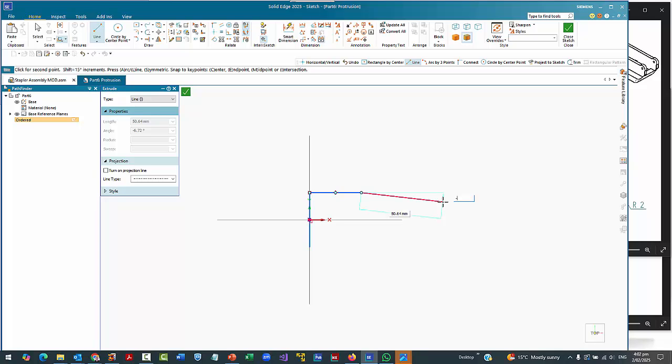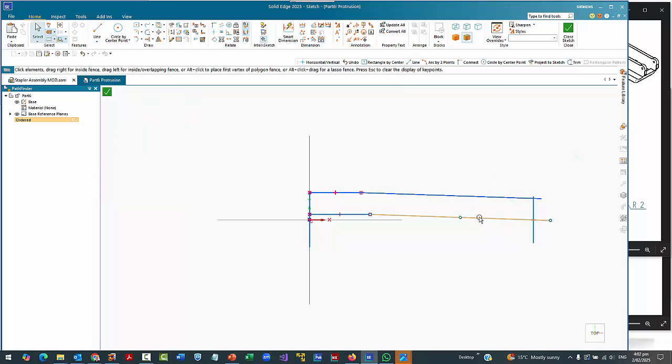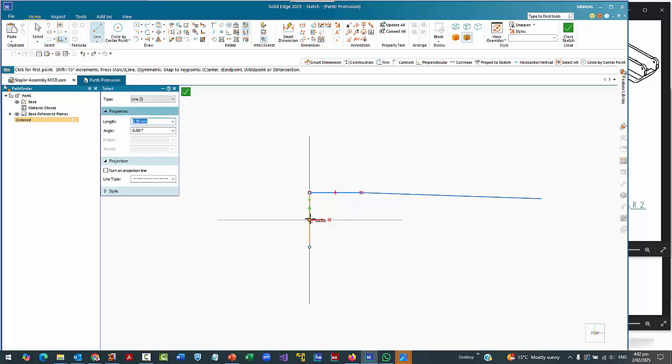So again, -2 degrees, right mouse click to reset, still on the line command, coming off that center point. If I go here, S for symmetric, and this wants to be 30. Something weird happened there, so we'll come back to here. Picked up off geometry, so you've got to be careful of that. And then we come out horizontally.